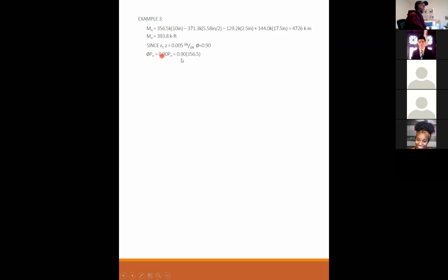So phi Pn is 0.9 times Pn, 321 kips. Phi Mn is 0.9 times Mn, 354 kip-feet. Any questions on point D?